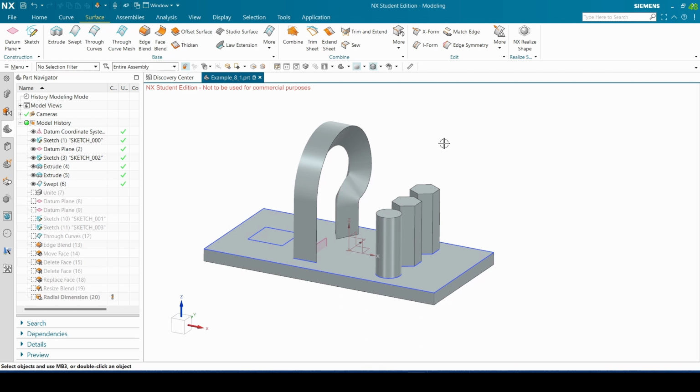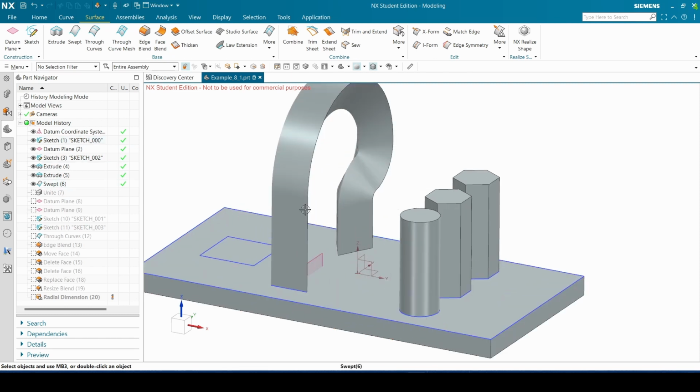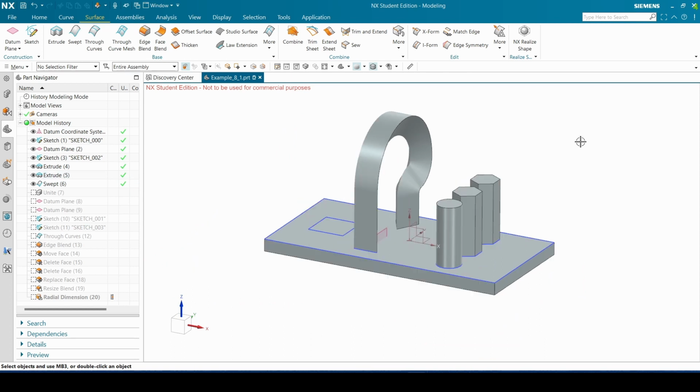One caution that I'll give you is if you create a part with sweep or swept and then need to draw it, it's quite difficult, because it doesn't handle it the same as a normal face. It doesn't say, here is a straight line and then there's an arc and then another arc and so on. It's all one continuous face. That makes drawing a bit more difficult.